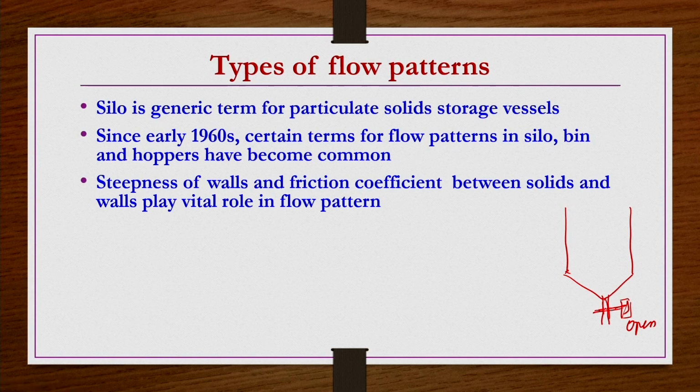So, you have a kind of feeder, whatever this opening is through which the material goes out, that is known as the feeder with respect to the storage and conveying of solids, right. A feeder is not something that is coming in from the top, that we do not call a feeder. So, the gate at the bottom, whatever opening we have at the bottom, that we call a feeder.